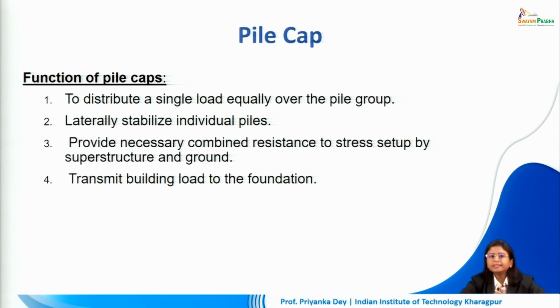It also provides lateral stability of individual piles, holds them in position. It provides necessary combined resistance to stress which is developed from the superstructure and the ground, and it transfers the building load to the foundation.